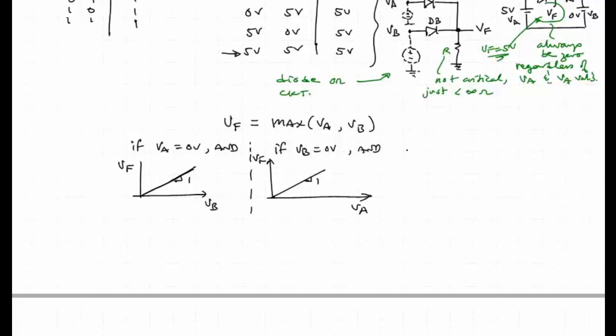What you really should have, if we define a VO high and a VO low, a VI high and a VI low, oops, did that backwards, and this is an OR gate with, we'll say, VB equal to 0, and so we'll sweep VA here. What we should have is something that falls in these regions here. Actually, let me redraw this one last time, because those VI high and VI low should be more closely together. In other words, they have to fall inside here.